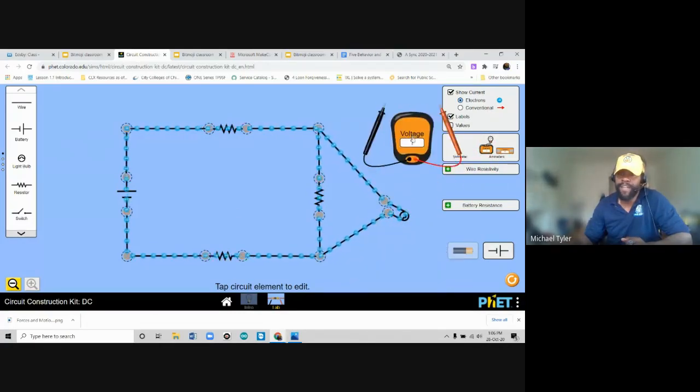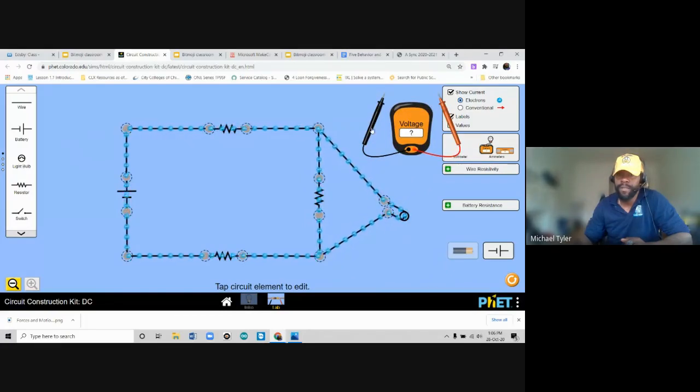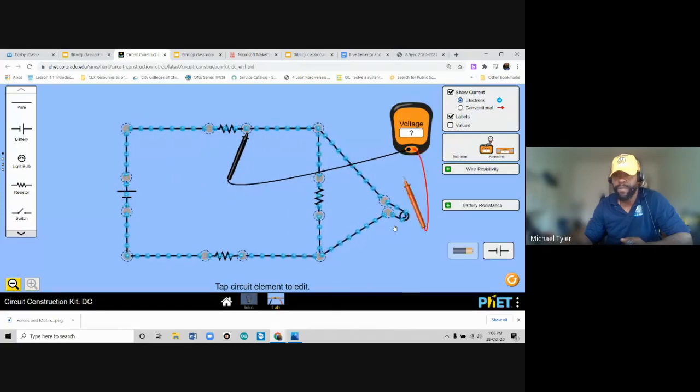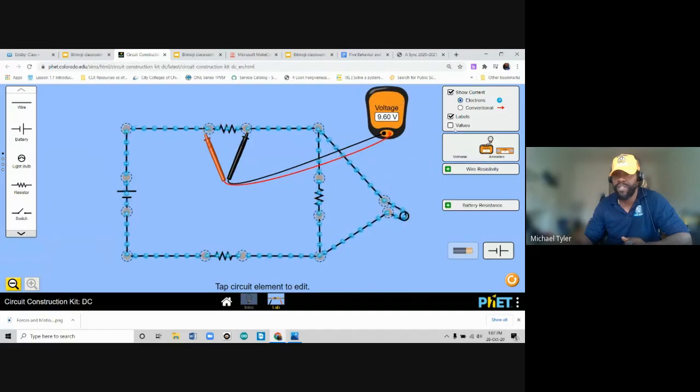We have to connect some tools to this. So I want to see how much resistance is on resistor 1. You take your black lead and put it on the negative side of the resistor, and you take your red lead and put it on the positive side. That's a voltage drop. That's what we had in our calculations, those V1s, V2s, V3s. You can do something like this in a household. You can really get a powerful job.